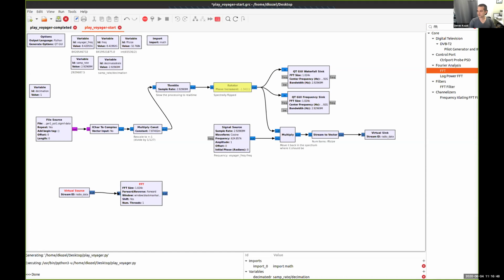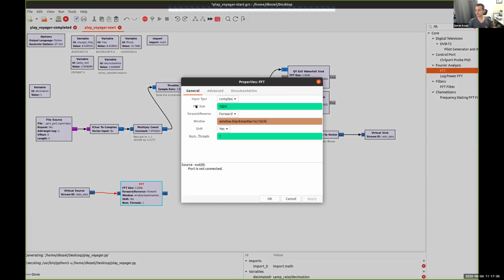You can either click and drag, or you can click on the output, then click on the input. Either one works. We have this variable which defines the FFT size, and we're just going to reuse that in each of these. So where it says FFT size here, we just type in the new value. And if you hit apply, the arrow went black.